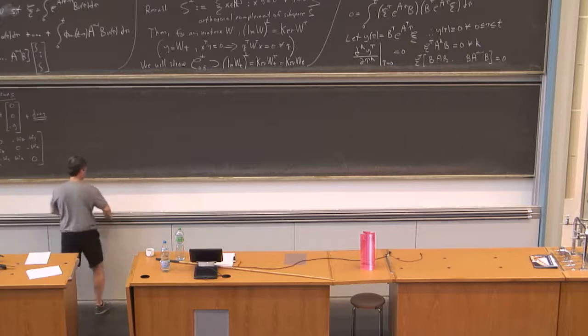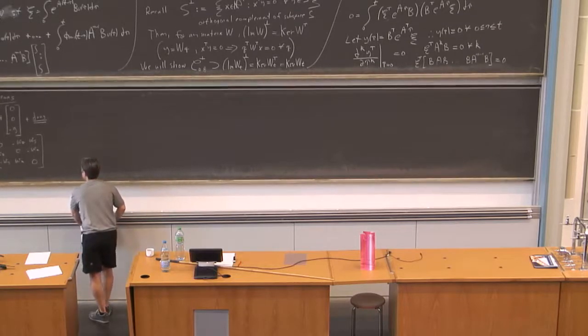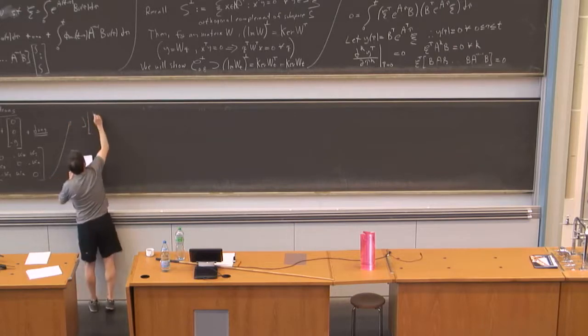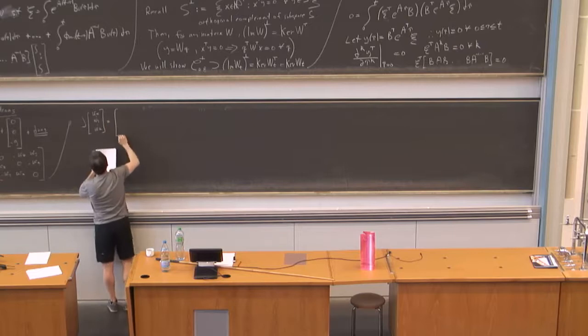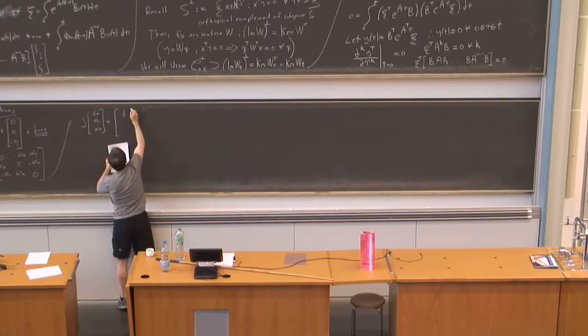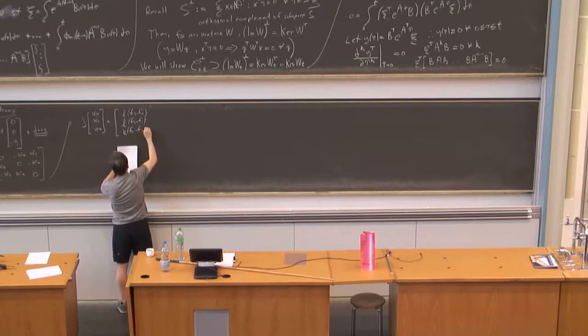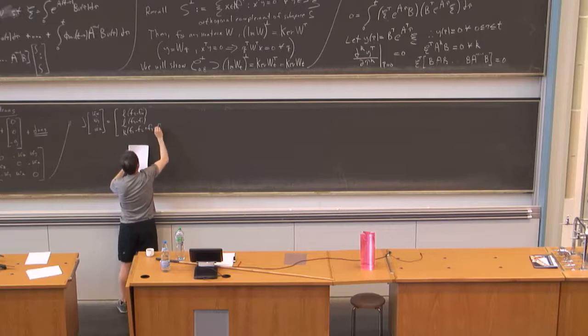And for that, I have J times omega x dot, omega y dot, omega z dot is equal to L (F2 minus F4), L (F3 minus F1), k (F1 minus F2 plus F3 minus F4).